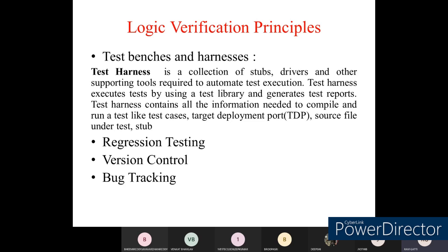What do we mean by wafer level? When you do the fabrication, we discussed the fabrication of the N-well process and the fabrication of the P-well process. When we do the fabrication of any basic elements, it is through the use of a silicon wafer. If there are any defects in the fabrication of the silicon wafer itself, then whatever circuit we implement through those defective wafers will directly affect the performance of the design of a VLSI subsystem. Therefore, it is necessary to do the diagnosing or verification process at the initial stage itself. That we call wafer level verification.